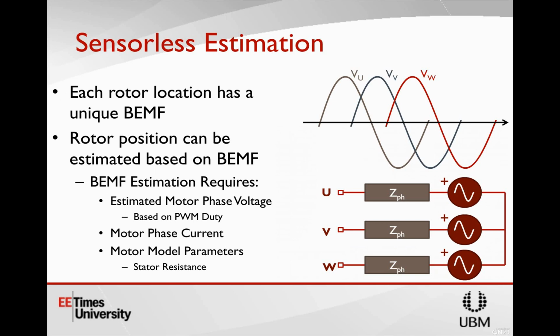And then in terms of filtering, you don't really want a lot of filtering, because you want that signal to be very, very quick. The biggest filter you're going to need to worry about is the PWM noise. You can deal with noise at that level, but you'd still want to have that current feedback extremely quickly. That way you don't have to worry about whether you've filtered away the fast dynamic response you need in order to meet your application objectives, while also filtering out any kind of noise from the PWM.